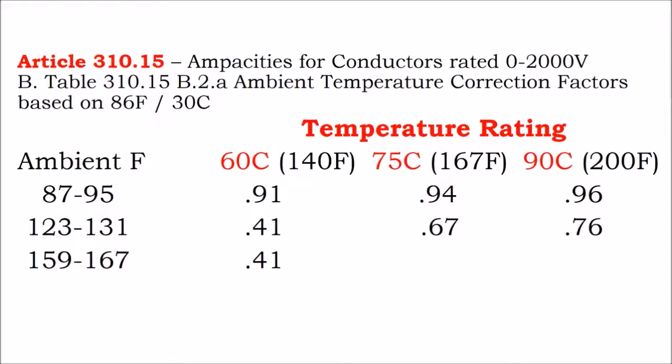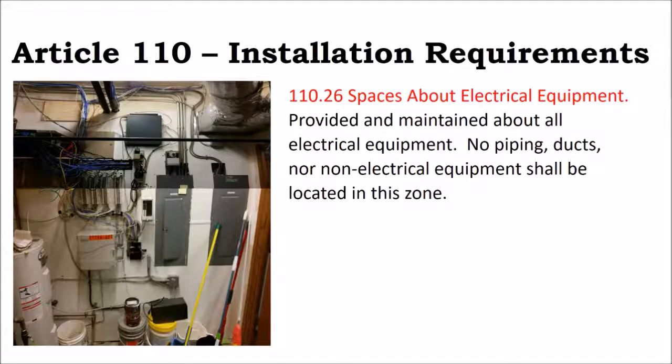It's more efficient and it generates less heat. And so in solar design, and when you're transmitting electricity from a generator to its point of use, you're balancing the environmental conditions, you're balancing derating the conductors, but then there's also efficiency, where often you're upsizing the cables anyway in order to make the system a bit more efficient. So we'll run through these calculations as we get into those sections a little bit later on in the program.